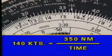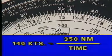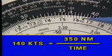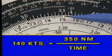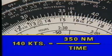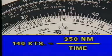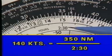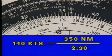Then look under the 3.5, or the distance of 350 nautical miles, to find the time in minutes. In this case, it is 150 minutes. Notice that you have to add a 0 to the 15. 150 minutes can be quickly converted to 2 hours 30 minutes by referring to the C, or hour scale.